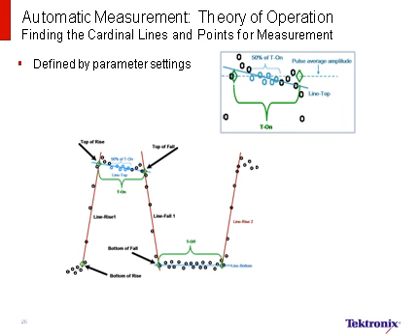Once the pulses are detected, we can model and construct the 4 cardinal points and the 4 lines necessary to create all the measurements. These cardinal points are the bottom of the rise time, the top of the rise time, the top of the fall time, and the bottom of the fall time. The lines are the slope of the rise time, the slope of the on time, the slope of the fall time, and the slope of the off time. A pulse cannot be determined to be a pulse unless a subsequent rise time is found on a second pulse.